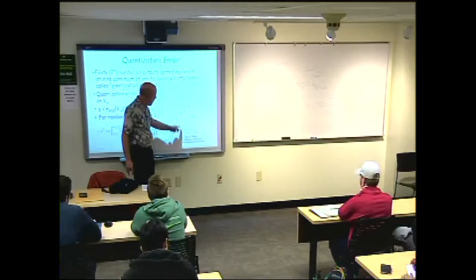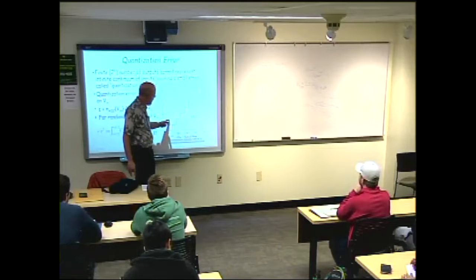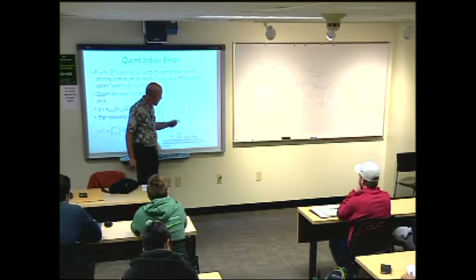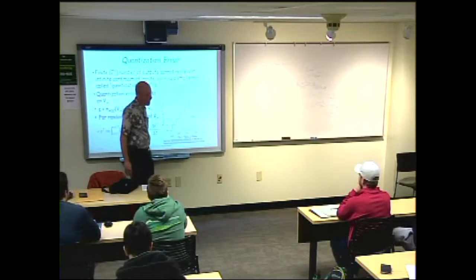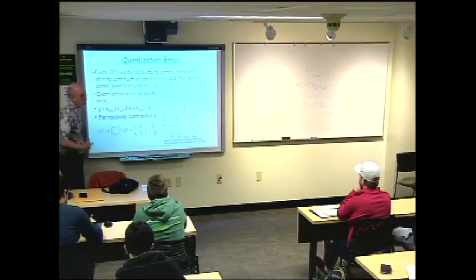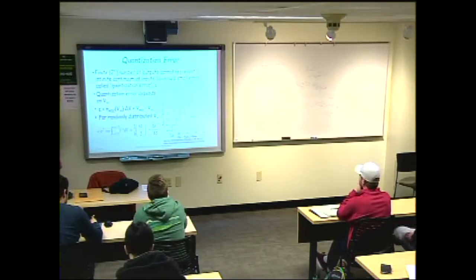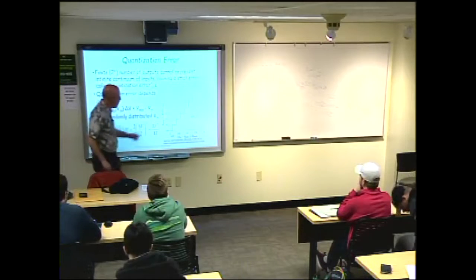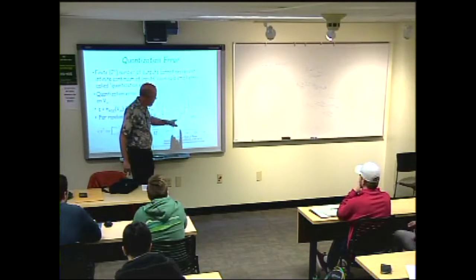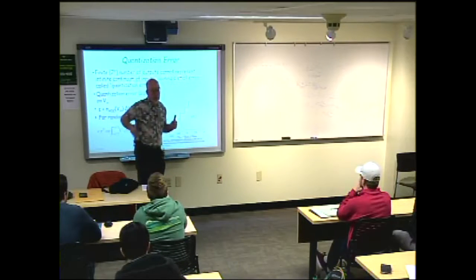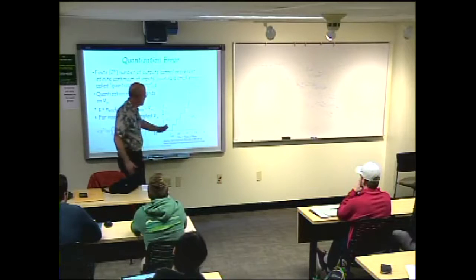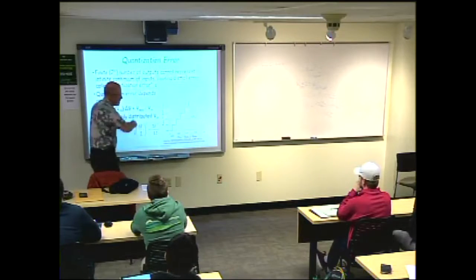But if I'm, say, over here where this blue line is, and what I'm getting out of it is a 0, 1, 0 representing that particular voltage level, when the real input is up here, I have a quantization error that's almost half a step size, and that's what epsilon is. So the error actually depends on precisely what the input voltage is. And if you subtract the red curve from the green curve, and then you integrate over some evenly spaced set of bits here, you'll get a sawtooth wave.